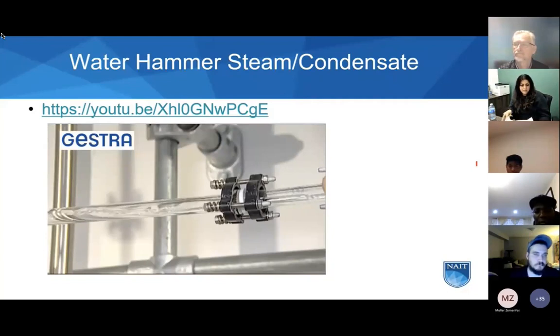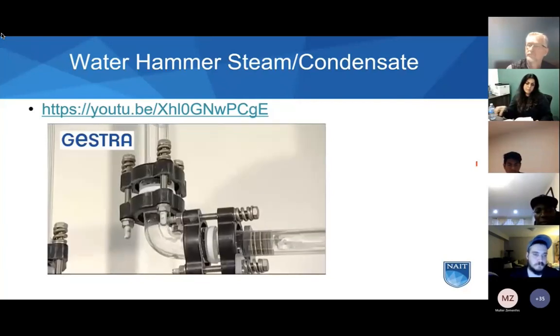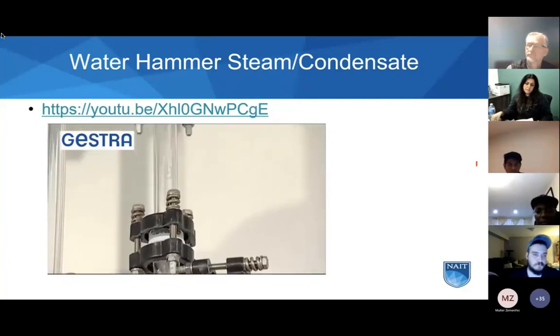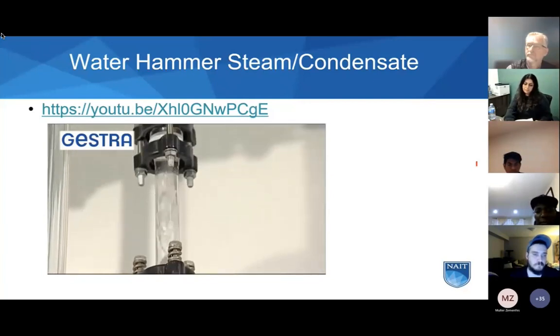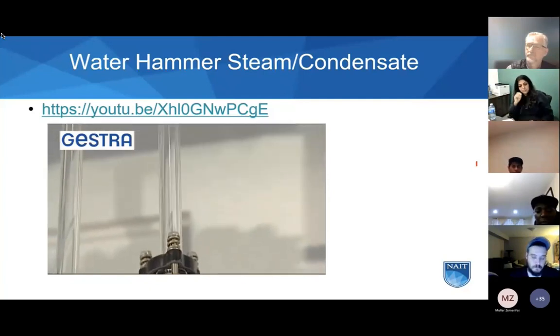The water quantities accelerated in this way must now be stopped in fractions of a second. It's possible for pressure shocks with peak values of more than 1,000 bar to be created. This becomes noticeable through the visible shocks and explosive sounds. The shutoff valve must be opened very slowly to ensure that the number of steam bubbles passing into the water is kept as low as possible.